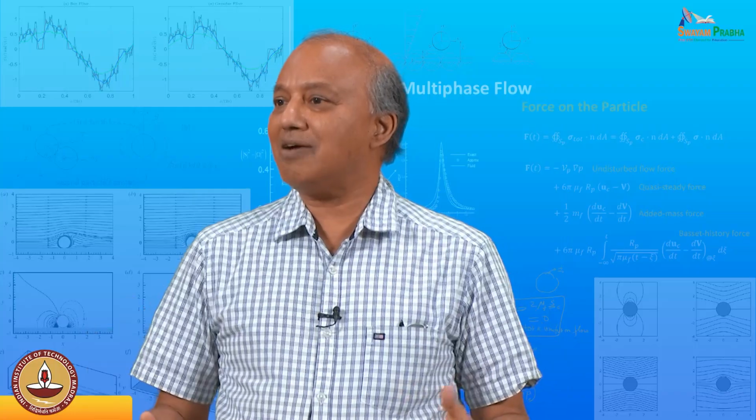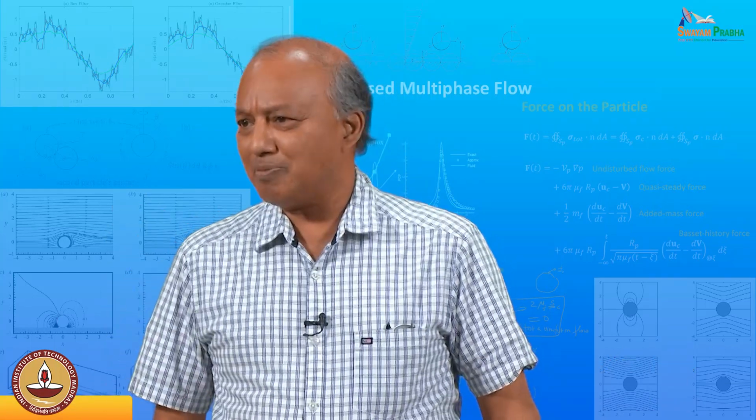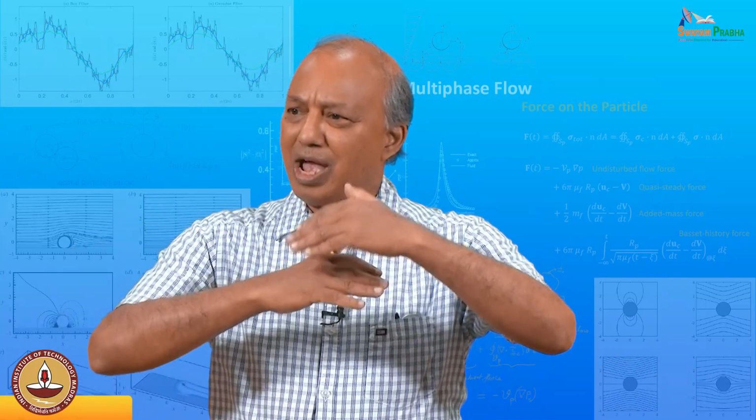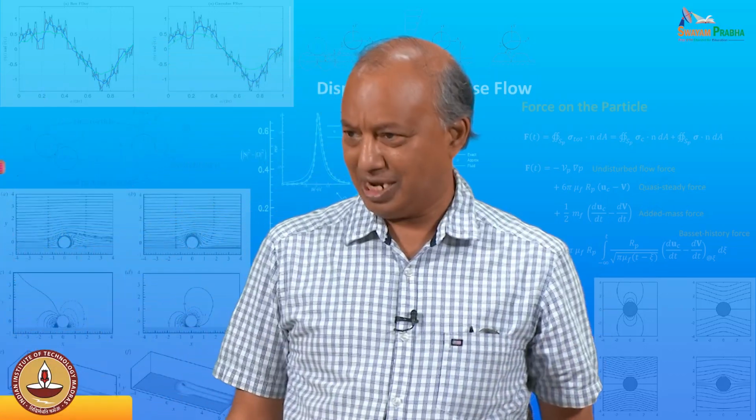So, there is no individual particle once you do an ensemble average. You are just talking about an average, but you will know that, hey, this spot has 10% volume fraction. Some other corner, if particles hardly ever come there, there the volume fraction will be low. But what I am trying to say is the ensemble average erases all the details about any particular experiment. If there is a wave of high particles sweeping the region, you won't know all those details.